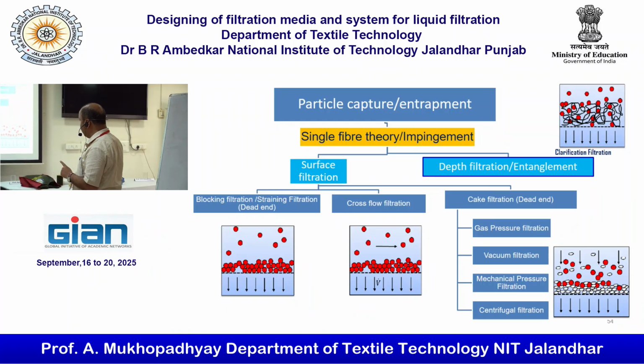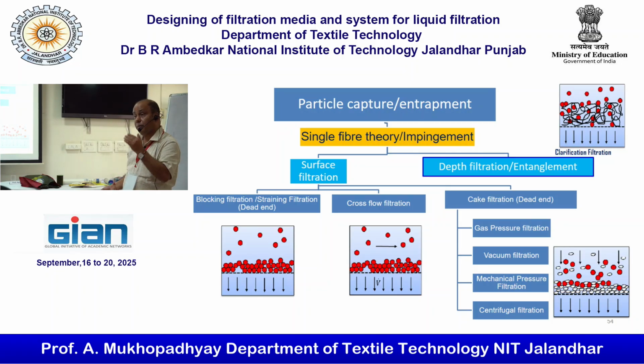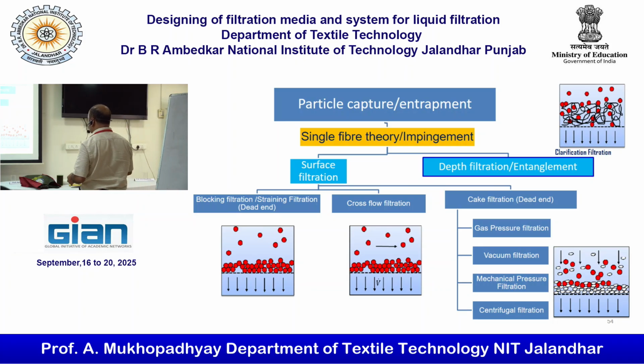Here I am talking about centrifugal filtration where the media is used, because we are taking the help of both: high centrifugal force, as well as the media role is important. So whenever the sludge content is more, we will have to opt for mechanical pressurization, pressure filter, or centrifugal filtration. These are the options.